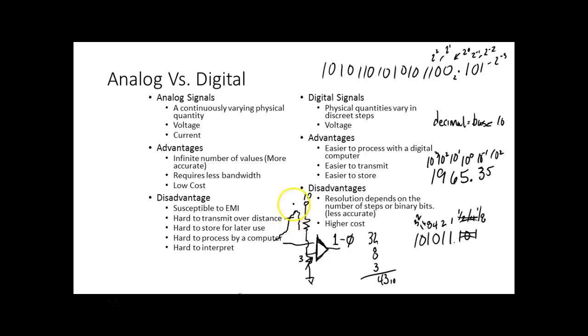And a lot of times this will be built into the sensor. So the sensor will have a sensing element out here, whatever it's sensing is an analog quantity, and the comparator is built into the sensor. Then it's got an output. So it's going to have a common, a power lead, and an output lead. And these are what we call 3-wire sensors. So if you ever see a sensor that's got 3 wires on it, then it's some type of solid state sensor or electronic sensor, right?